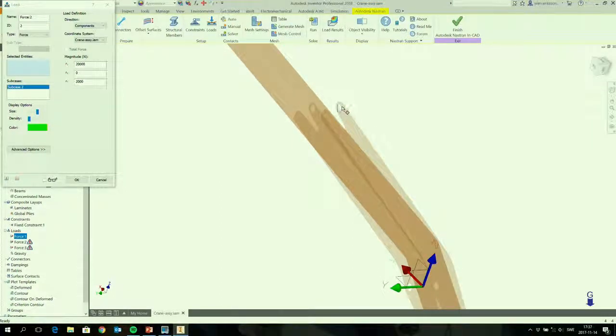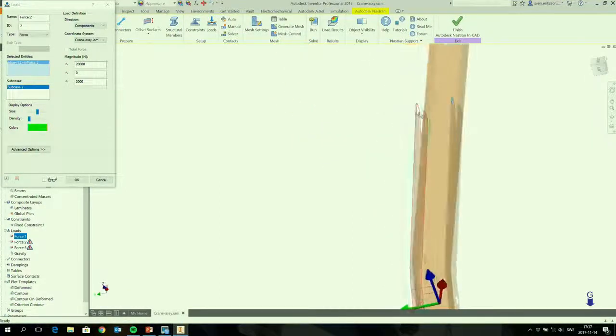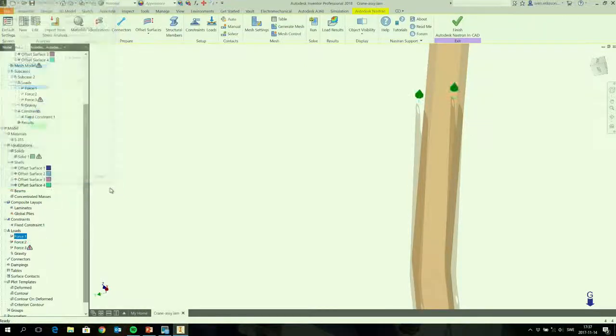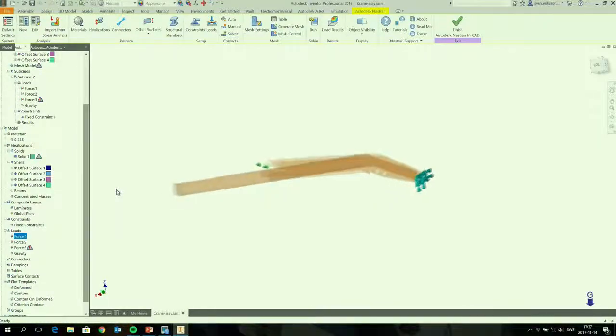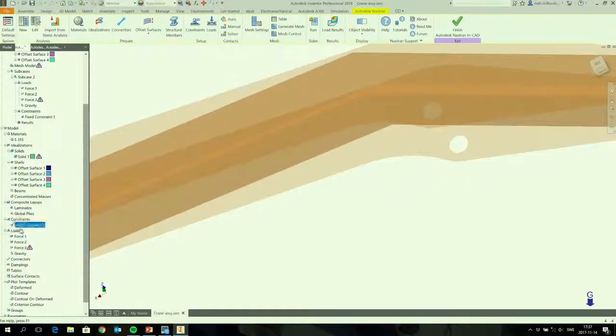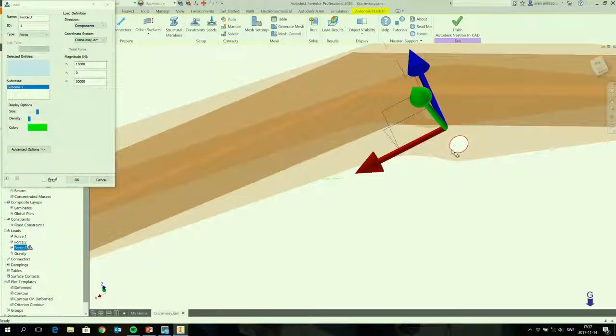That is this one. Put on that one. And what you need to remember now, in Nastran, you need to mark total force. If you don't, you'll get the full load on each. So if we mark that one, it works fine. And then we take the last one. And I forgot this almost every second time.